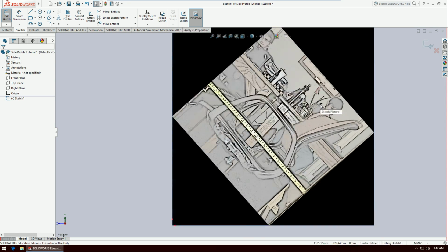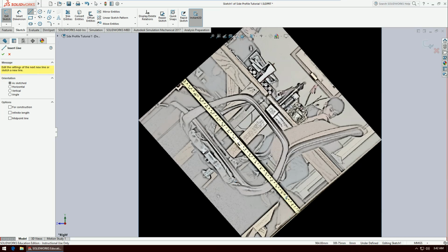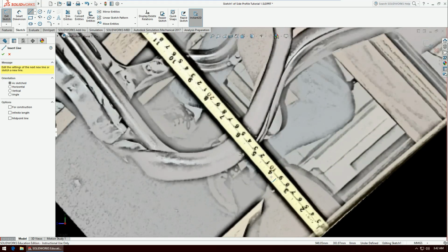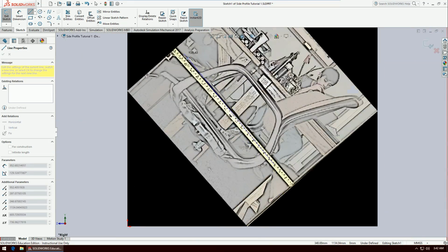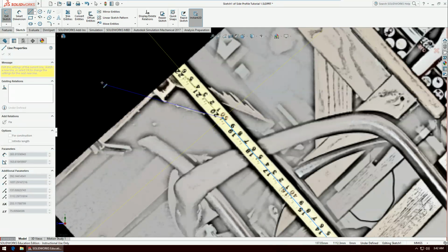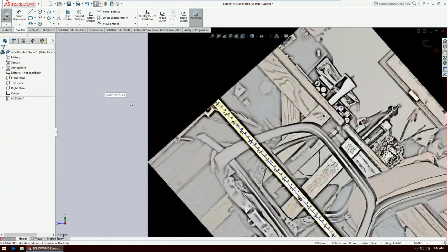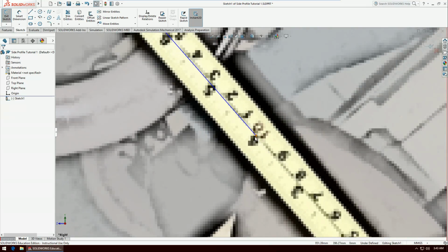Now I'm going to scale the picture. You can see when I took the picture I had taken it with a tape measure there so that I could scale the picture later. I'm going to draw a line along the length of the tape measure, starting at something like 10 centimeters, and going down the line to 50. You'll notice I'm using as much of the tape measure as possible in order to reduce the error in my measurements. Just make sure that it is actually at 10. Yep.